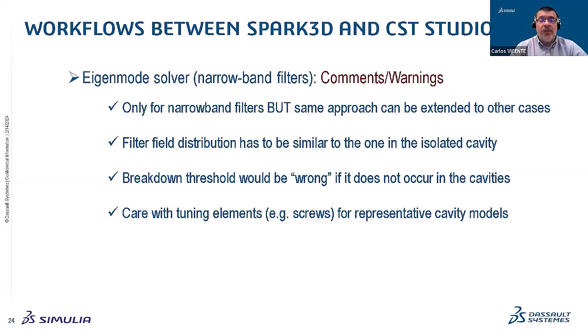And of course, in this case, for instance, I show you have tuning elements, and you have to tune the screws to get the final filter response, and this can add more inaccuracies to this workflow. But you can see that in this particular case, these changes in the screw length did not have a critical impact on the breakdown power level.